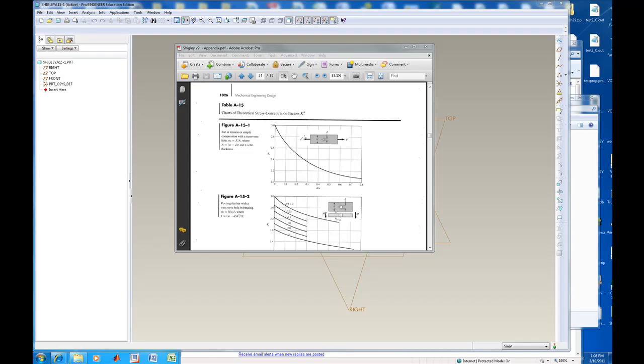And because of the overall geometry and loading of this thing and the nature of it, we're going to be able to use several simplifications. First of all, because of the double symmetry, we're going to be able to use a quarter model, a 1/4 model of this thing. And also, because everything about this is planar, we're going to be able to treat this as a plane stress model. So we'll look at all the details for that. So let's move the picture out of the way and get started.